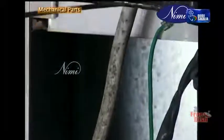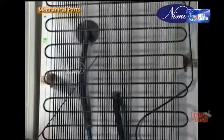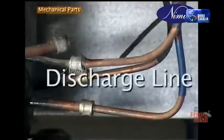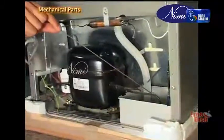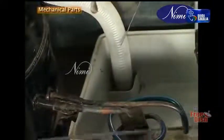Suction line. The line through which refrigerant flows from the evaporator to the compressor. This is toward the low pressure side of the system. Discharge line. The line between the compressor and the condenser is called the discharge line, which is toward the high pressure side of the system.